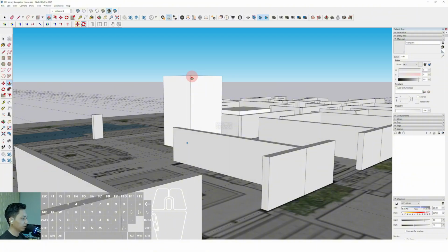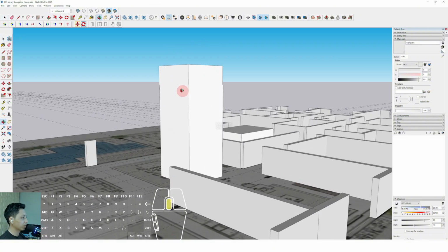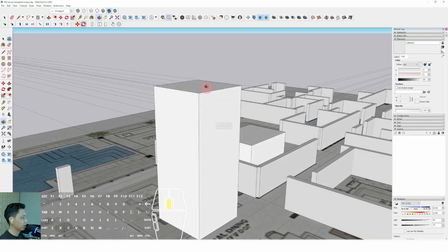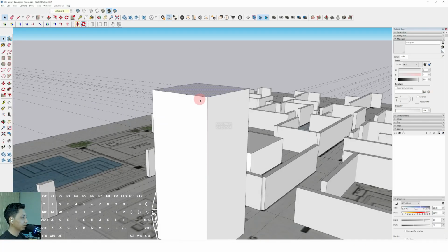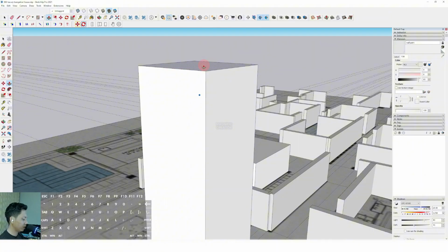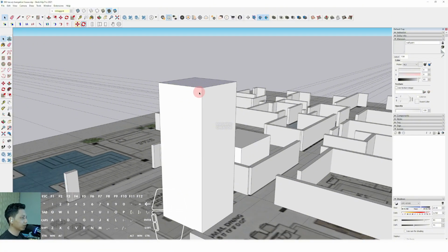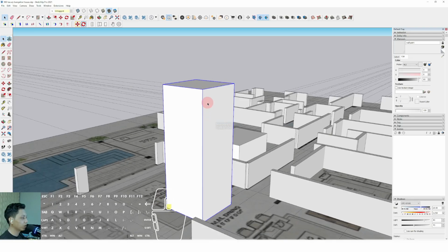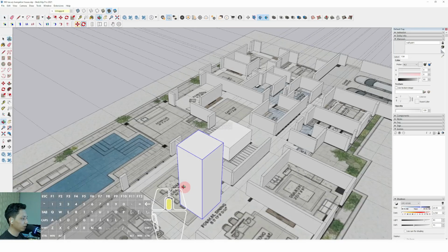For example, we can set it around 3.6, maybe, for the temporary elevation, 3.6 meter, or maybe 4 meter. We can set it 4 meter, so we can add more 400 millimeter or 40 centimeters to complete the 4 meter elevation from the floor to ceiling.